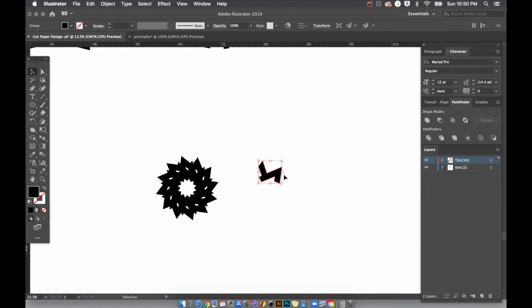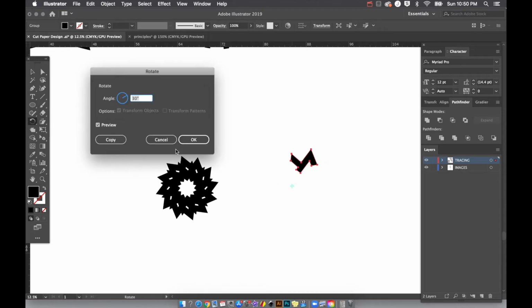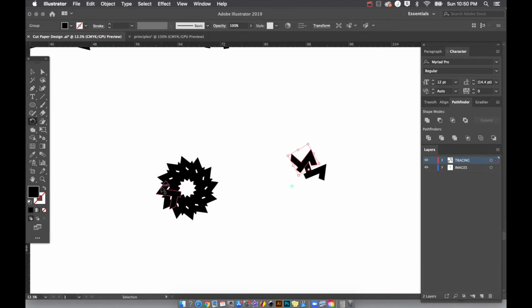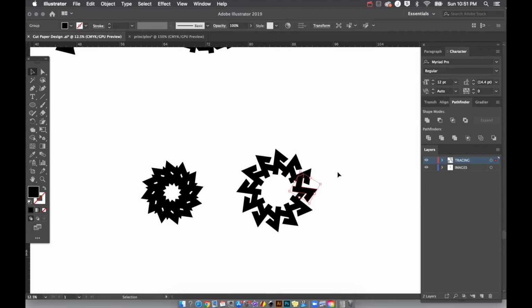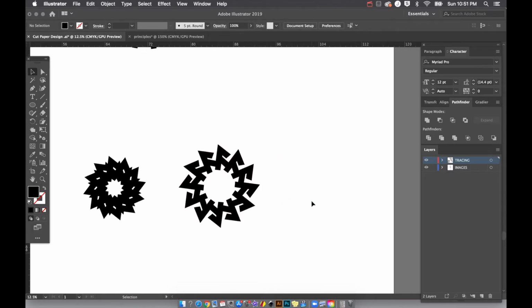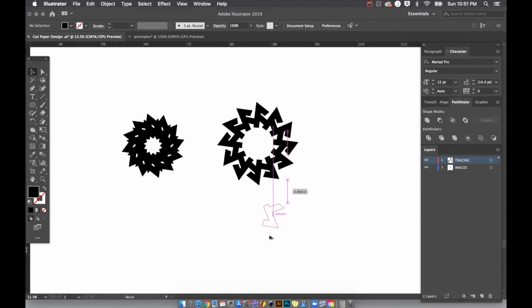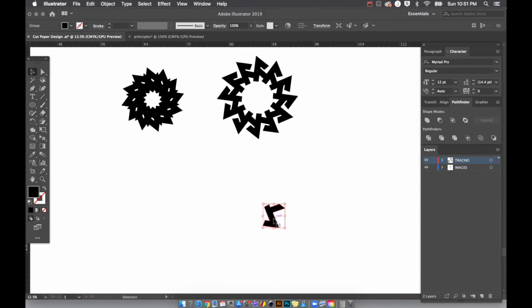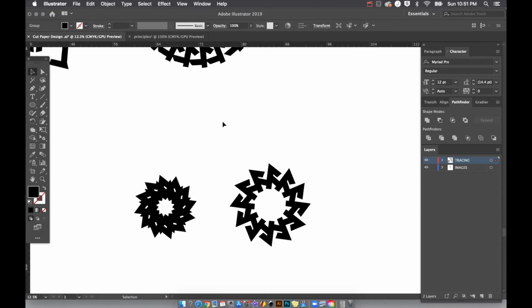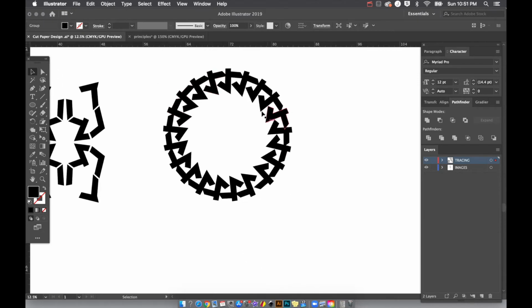This time using a rotational pivot point that's a little bit outside of the center. Use my rotate tool, Option, click. I'll do a 30-degree rotation by copy, and Command D to repeat that all the way around. Now, it automatically leaves these as individual shapes, which is something I really like about this technique, and it allows me to work with many more pivot points than just the ones that the 9 options that the rotational symmetry allows.